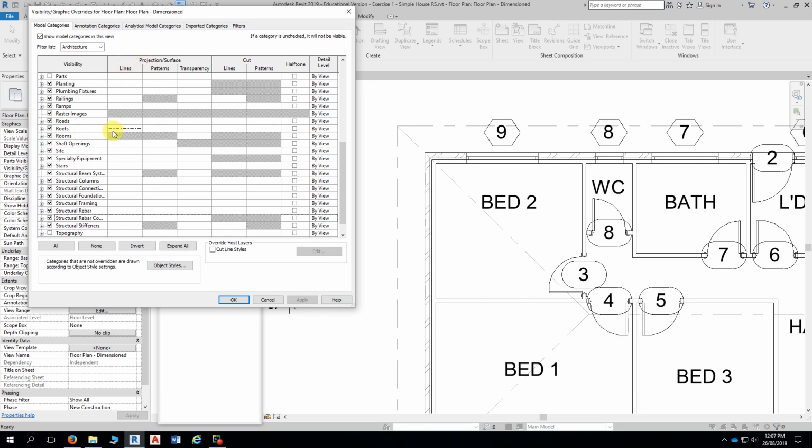See the dashed line there? What we just did was we actually changed the roof outline to dashed or centre. Now, in doing that, see how it's now showing here in Visibility Graphics.